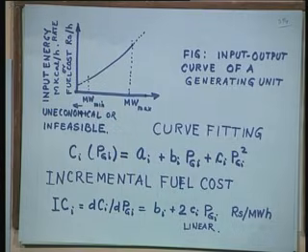It may even be technically infeasible to generate slightly less than a particular number. Forget about economy. Similarly, maximum: if it is a 100 megawatt unit, you can't generate 500 megawatt, otherwise it is a miracle. Nobody will purchase bigger size units. For some time, yes, you can have a 125% rating, you can work, but not all the time.